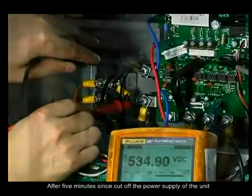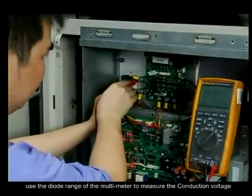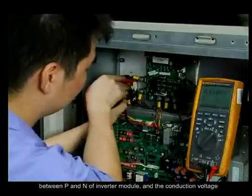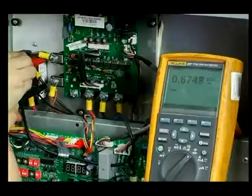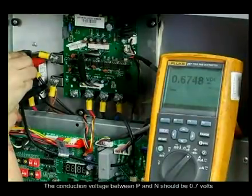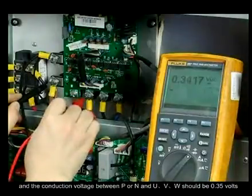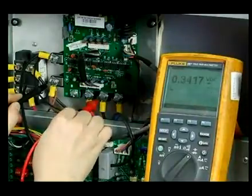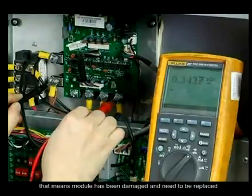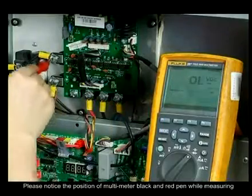normal. After 5 minutes since cutting off the power supply of the unit, use the diode range of the multimeter to measure the conduction voltage between P and N of the inverter module, and the conduction voltage between P or N and UVW. The conduction voltage between P and N should be 0.7 volts, and the conduction voltage between P or N and UVW should be 0.35 volts. If the measured value is 0 or infinite, that means the module has been damaged and needs to be replaced. Please notice the position of the multimeter black and red pens while measuring.